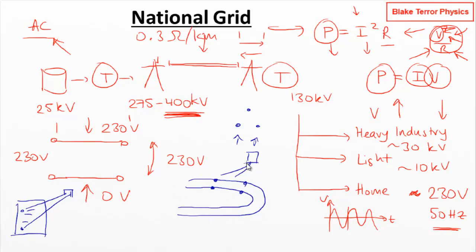It does create other issues, because then we have bigger plugs in the UK because we're having to put a fuse in every plug, which makes them bigger and bulkier. Now we're putting more of the responsibility on managing each appliance and each connection to the ring main. We've moved it away from this sort of centralized fuse board onto each individual socket. So things have changed a bit.